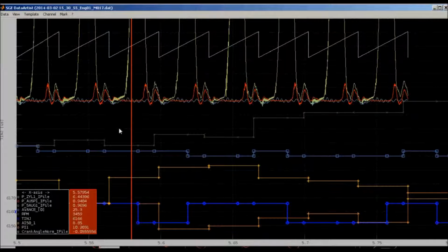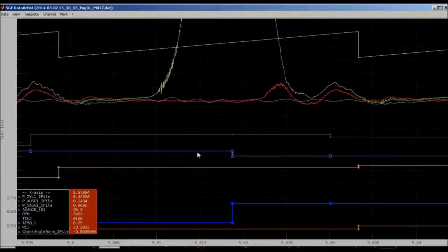As a special feature for combustion analysis, we have the possibility to automatically load indication files in parallel with the engine management system measurement files. The crank angle-based files are automatically calculated to the time-based system of the measurements from the ECU. This way we get a synchronized view of the ECU measurement data and the indicating measurement data, completed by an additional channel showing the crank angle position.